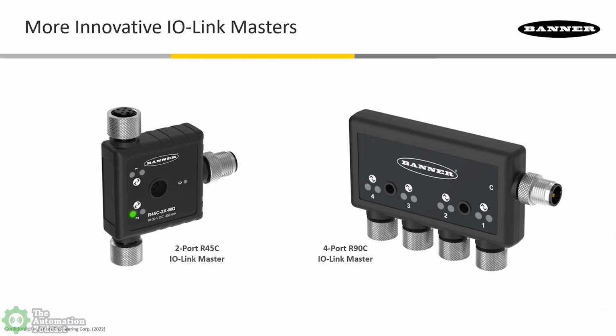If you want to add more IO-Link devices and have that one Ethernet connection going back to your control system, you could add these to that Modbus RTU port on that IO-Link master. These are serial IO-Link masters. There's a 2-port, so you could connect 2 IO-Link devices, and on the right there's a 4-port. On that male connector, you have that RS-485 or Modbus RTU communications going out.